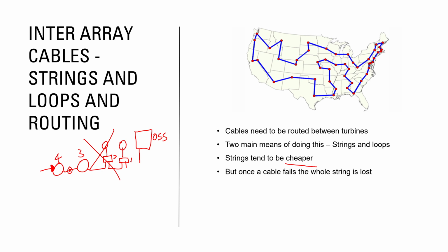So you need to install a noisy great diesel generator on that turbine, and you need to drop that there with a ship, and it needs fuel, and so you need to keep filling it up with fuel, and you need to do that for as long as those turbines don't have power. Now that can be a very expensive job to do, not because diesel generators and fuel are particularly pricey in the grand scheme of things, but because in bad weather it may be a while before you can get to these turbines. So if, for example, the turbine's been loafing around with no power for a while, the first thing the manufacturer is going to do is tell you your warranty is void. So that can be extremely expensive.